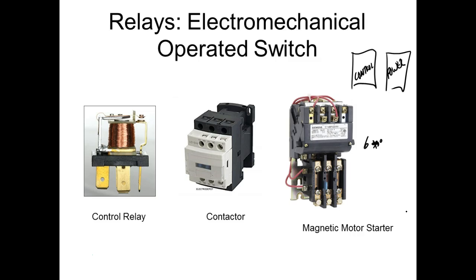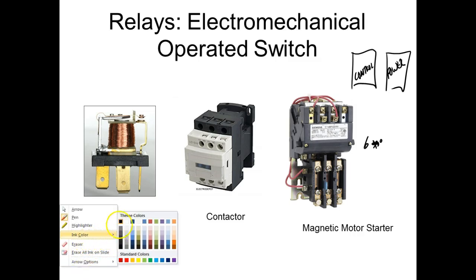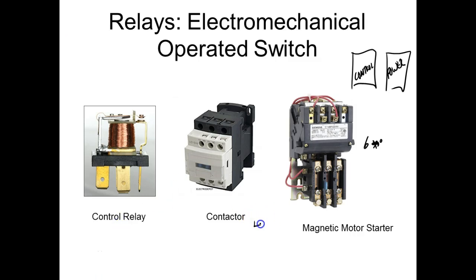And a lot of the relays we use in the industry are actually what we call double break contact. So we'll come up here and one contact would look like this, if I draw them vertical like this. And then we'd have something down here that they would be made up in. This would be a normally closed contact. And then we would wire it here. So this is conductors. So when this thing closes, we create a path.